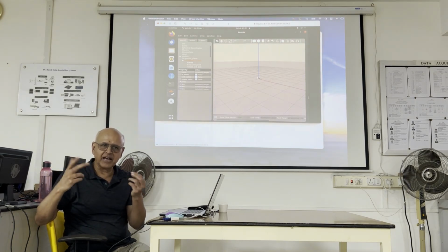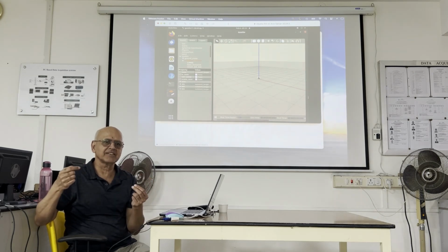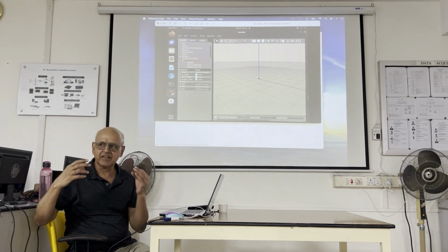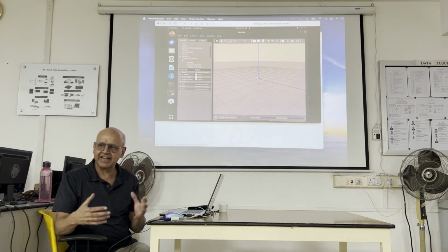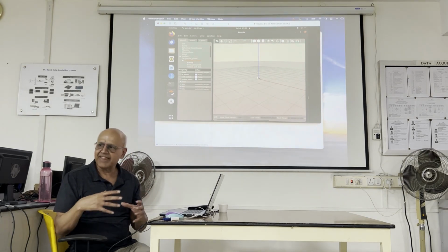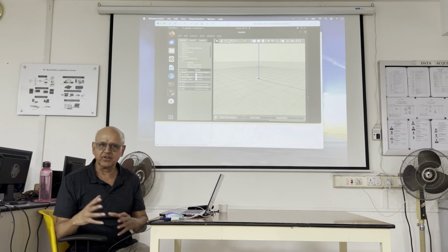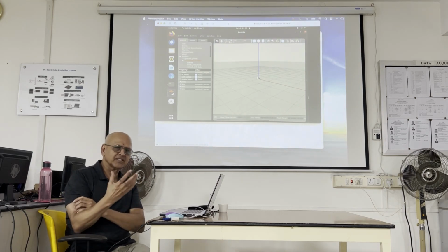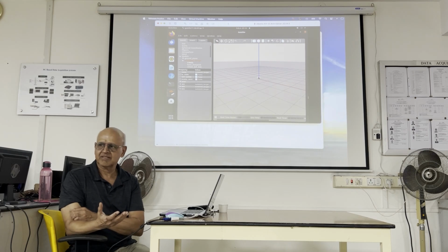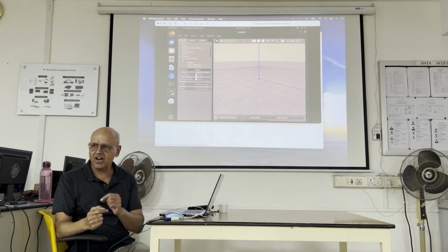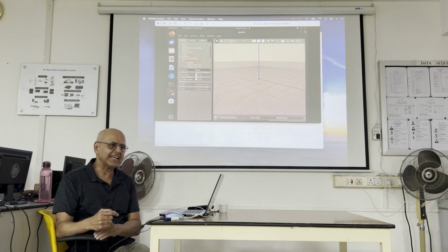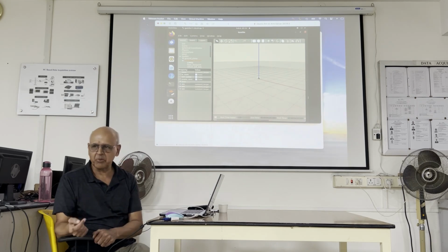Now if you are not happy with that, you can go to a 10,000 count encoder. After a certain point, you're wasting processing power because it makes no sense to know the rotation of the wheel to 1/10,000th. Because there are so many other things that are interfering, like noise, slipping, sliding, that it makes no sense to measure anything at that level. So in any engineering experiment, you only measure to the accuracy that makes sense. Okay, now, so odometry needs to be reported because odometry is the most fundamental way of locating where the robot is, localizing the robot.